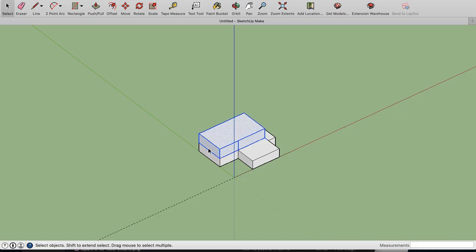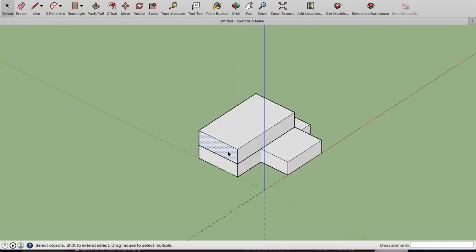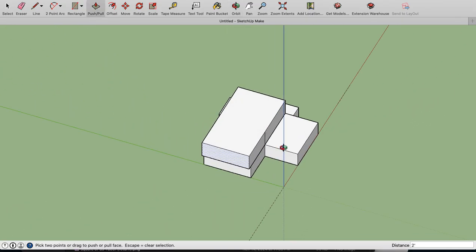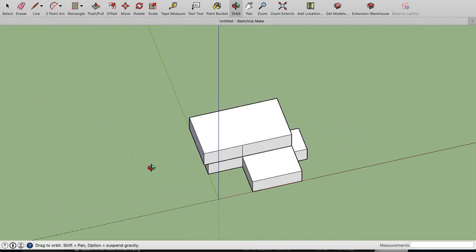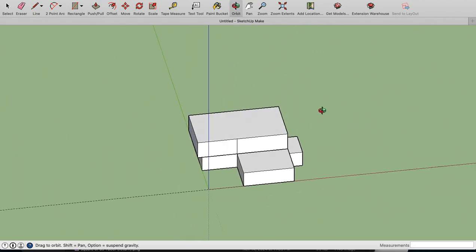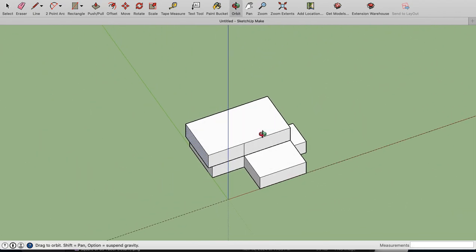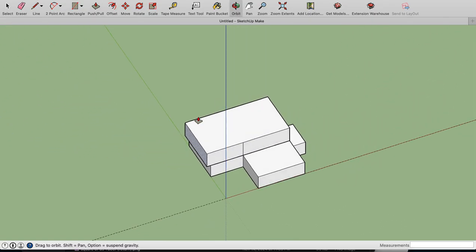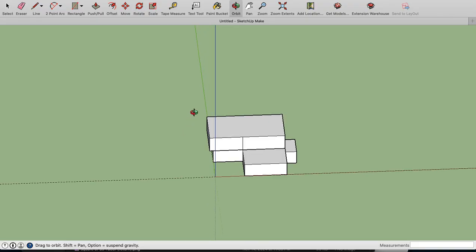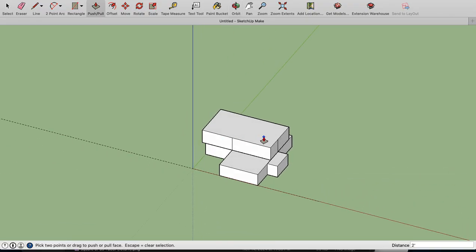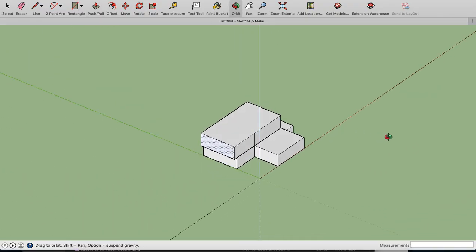The same thing could happen out here. It's possible in Part 9 that you can design this as a 2-foot overhang like this. So the same thing happens. The building dimension is changing for our horizontal and vertical axis on each story, and our calculations in the building code, this subsection in particular, can account for that. We just need to be really cognizant of what story we are actually designing, and when we're doing our calculations, we need to be sure that we're referencing the correct story with the correct building dimensions.